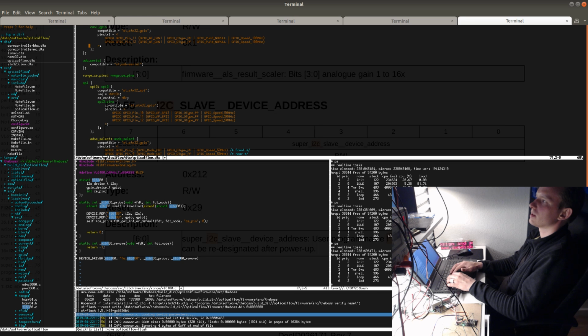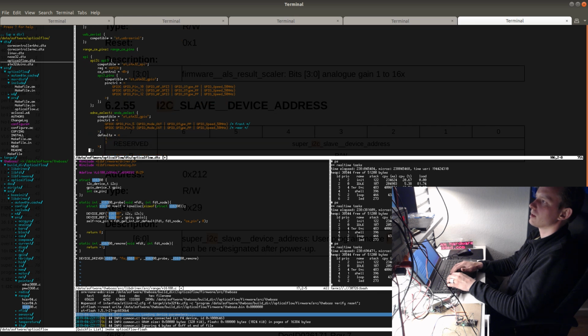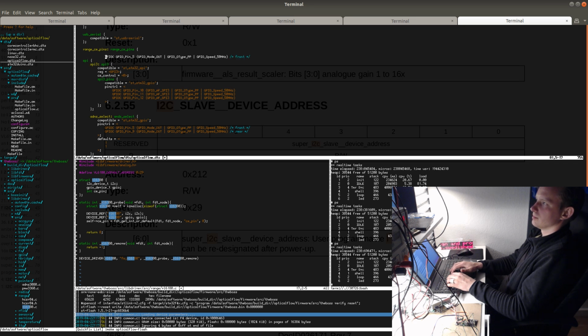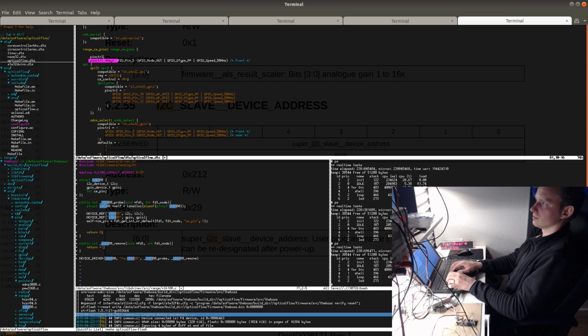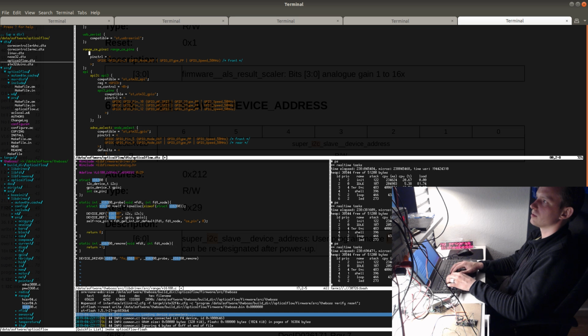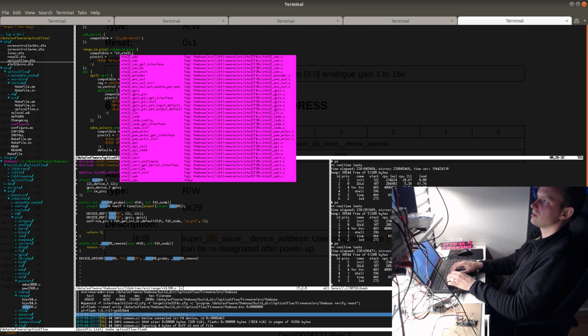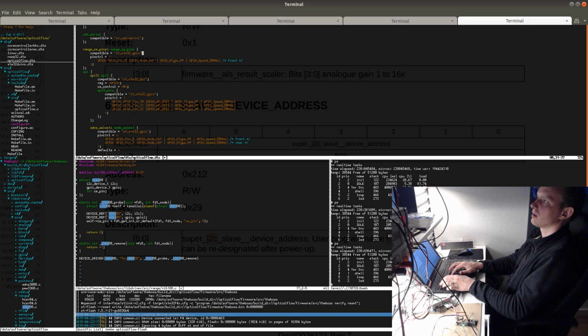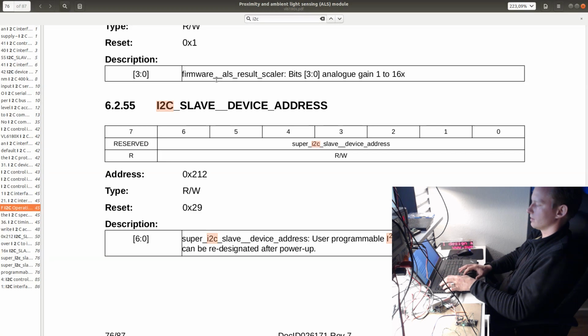Let's do this as an output, so I can just copy one of these. And this hooks up to my device tree-based STM32 GPIO driver, which I can reuse anywhere I want because I have written it to support the device tree. So let's call this the STM32 GPIO. And then I'll program the pins. So let's have a look here.